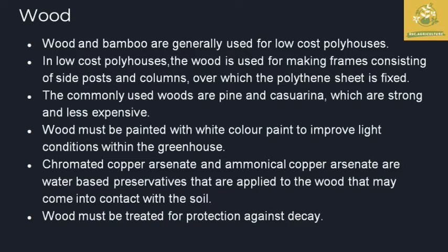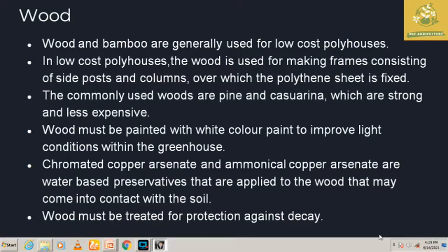Chromated copper arsenate and ammoniacal copper arsenate are water based preservatives applied to the wood. Once these are applied, decay and water absorption when the wood is in contact with soil are reduced, so the life expectancy is increased.